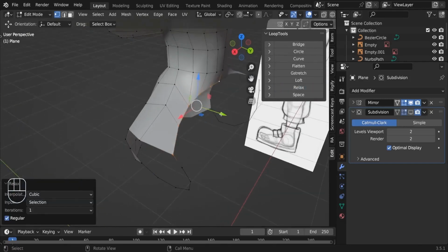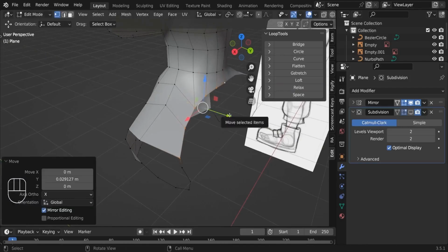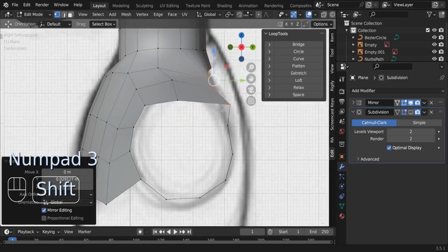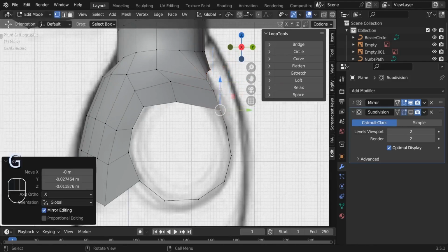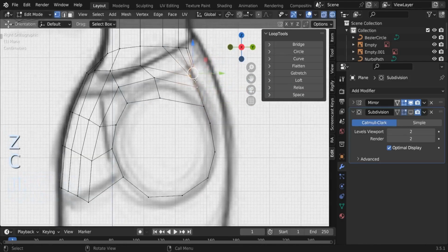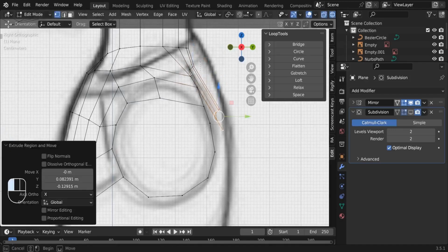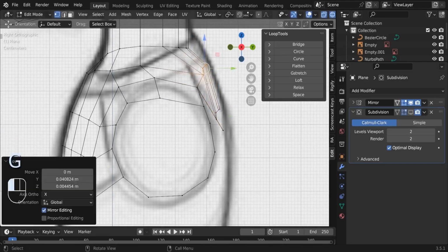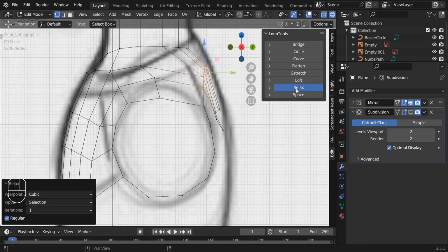Yeah, seems to be right. Push it back, press 3, take this single vertex back, switch to wireframe, select this part, you can extrude it here, or before extruding we can push them a little bit backward. Let's select them all, relax them again,